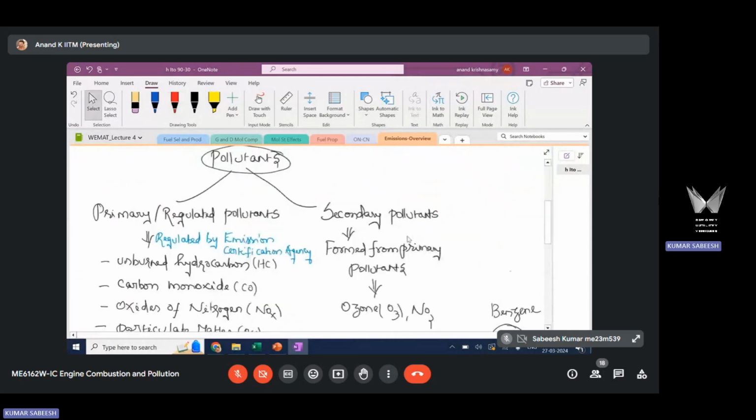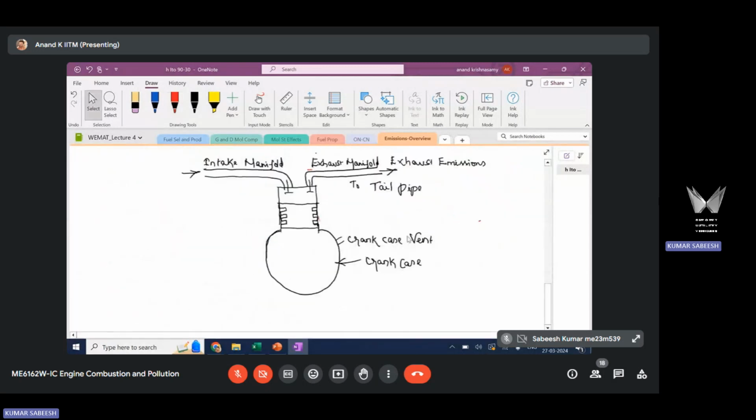Okay, so the crankcase is located at the bottom end of the engine. Here you have high pressure combustion gases. The pressure is so high here and the pressure is low here in the carburetor. So you have a delta P that naturally exists between the two ends. Piston is acting as a sealant. Piston is in fact sealing the high pressure combustion gases from reaching the crankcase. Otherwise, you will have a delta P gradient that allows the gases, including fuel vapors, to go from this end to that end. Although piston is sealing, perfect seal is impossible to achieve.